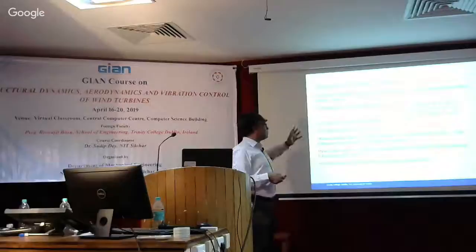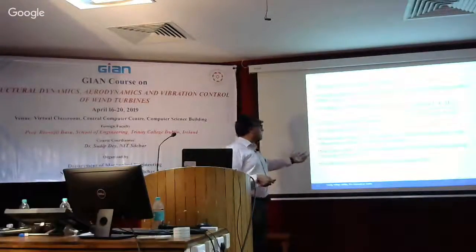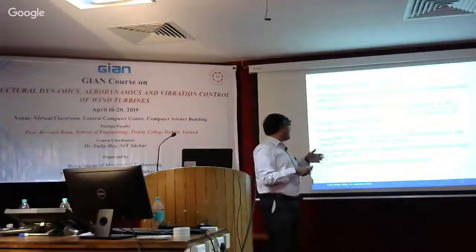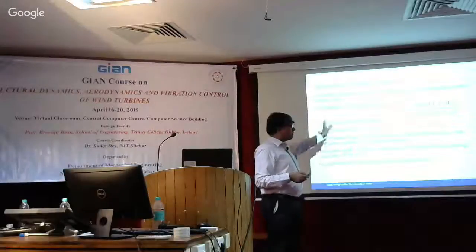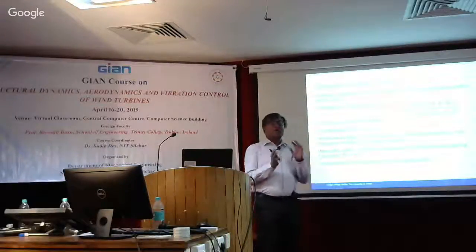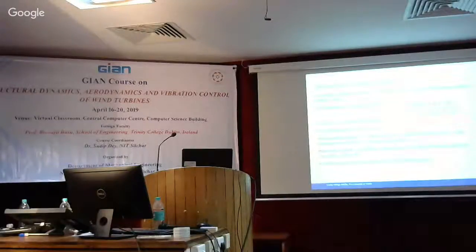Similar to the pitch controller, you can also have a generator torque controller. And in a similar way you can design filters. They can actually have broad-banded and narrow-banded peaks, and then combine the notch filter with these band-pass filters. So these are all kind of how your transfer function has to be designed. Meaning that how you're shaping this section. So for a single degree of freedom system, how do you want this to look like? You can design any arbitrary filter and correspondingly find the load or the input, like if this is like this and you want to make it something like this.